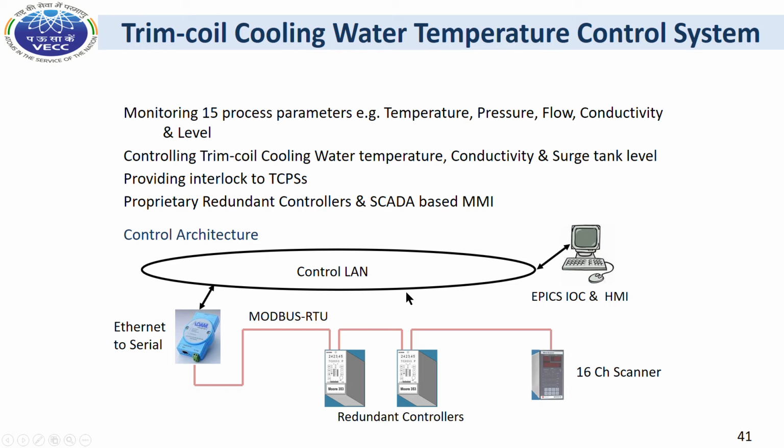The system provides interlock to the trim coil power supplies. Here, proprietary SCADA-based GUI communicates with proprietary redundant controllers in Modbus RTU protocol.